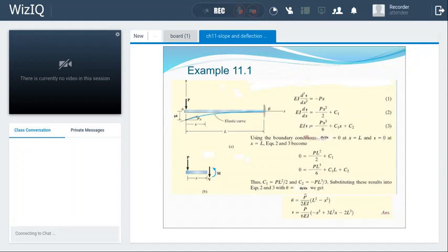Now finally your equation, which is in this form, we can say here EI dy by dx is equal to minus px square by 2 plus C1. Now C1 is PL square by 2. So we can say that EI dy by dx, so dy by dx is just written as theta, which is slope. So theta is, and then we can write this EI on this side, and this can be written as P upon 2 EI, and within bracket you will have L square minus x square on simplification. So this can be written after substituting the value of C1.